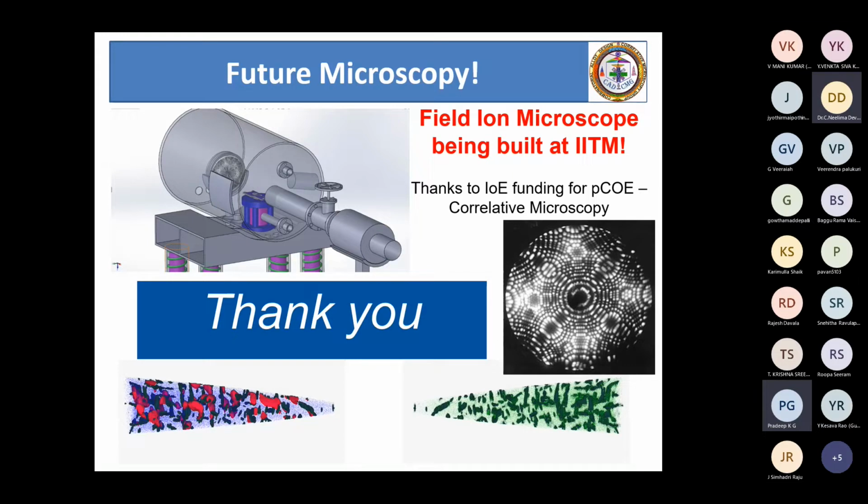Now, in the prepared condition, if we want to know why they are stable, then the first thing we have to realize is what their chemistry is, right? Unless we know that this nanoscale feature has a certain chemistry, we cannot say it is stable. Okay, sir. Thank you, sir. With a certain chemistry, we get a certain crystal structure for a certain size, and that crystal therefore has an orientation relationship with the matrix. Now that orientation at the interface stabilizes this particular nanoscale feature. I hope that answers what you wanted to know. Okay, sir. Thank you, sir.